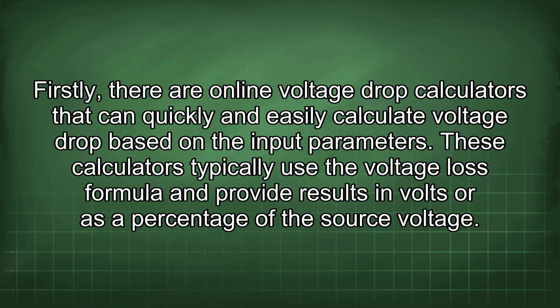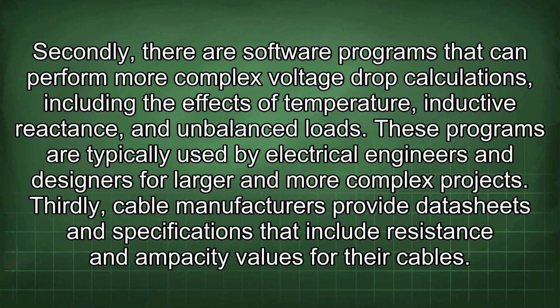Firstly, there are online voltage drop calculators that can quickly and easily calculate voltage drop based on the input parameters. These calculators typically use the voltage loss formula and provide results in volts or as a percentage of the source voltage. Secondly, there are software programs that can perform more complex voltage drop calculations, including the effects of temperature, inductive reactance, and unbalanced loads. These programs are typically used by electrical engineers and designers for larger and more complex projects.